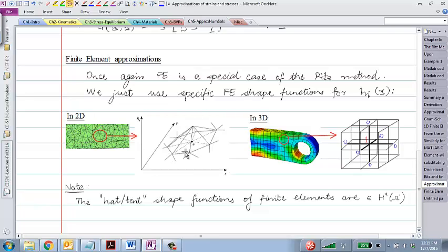There are derivatives in the x direction and derivatives in the y direction, and within each element you have a flat triangular face, right? So within each element, the derivative has one constant value, whether it's a derivative with respect to x or a derivative with respect to y. If we go to the neighboring triangle, that's again a face, but oriented in a different way, so it has different derivatives in the x and the y directions. So the derivatives are discontinuous, right?